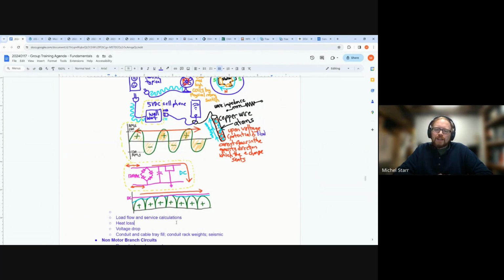Don't blindly do the calculation and then hand it over. So I said 200 watts or so for a panel board. If you can imagine, if you had a thermographer, like a red infrared imaging gun, and you were pointing it at a panel board that had all the circuits and all of them were turned on and all of them were doing load. The human body is about a 100-watt light bulb on average. So you think about how you'd feel, even just the sensibility of it. We're not even talking about very much heat. So just be sensible about these kinds of calculations, and the tons of cooling that could be specified can be a lot if it's not completely understood. For instance, in the technology rooms, IDF and MDF rooms, those rooms can be undercooled.